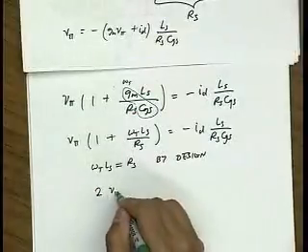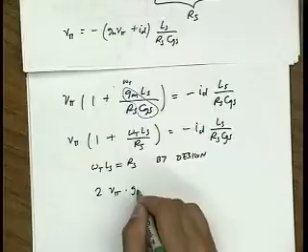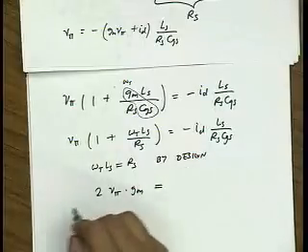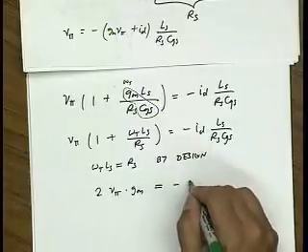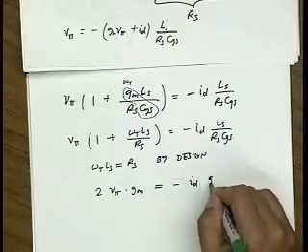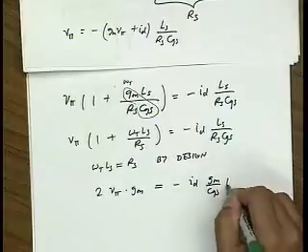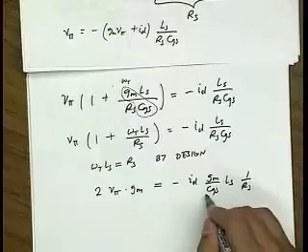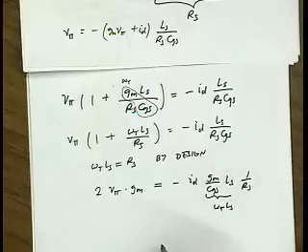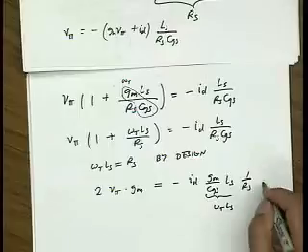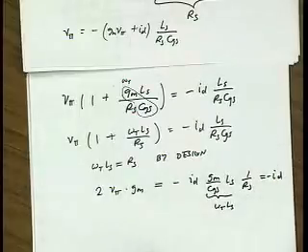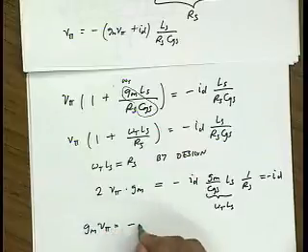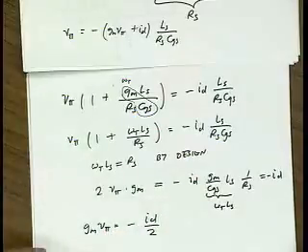So this gives me 2 V pi, and let me multiply this by Gm to give me the current through that transistor, which is minus I drain Gm over Cgs times Ls over Rs. And again, same thing here. This is omega t Ls, which is equal to Rs, so this is just minus I drain. So the interesting thing is that Gm V pi is half of I drain.